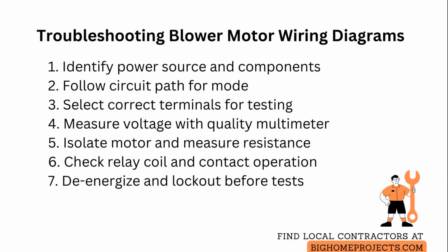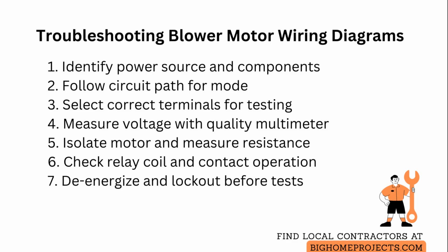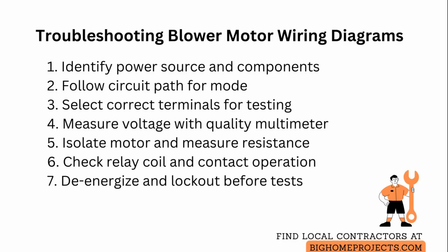Always de-energize, lock out, and tag out the circuit before performing any insulation or Megger tests or before disconnecting wiring to avoid false readings and to protect yourself.